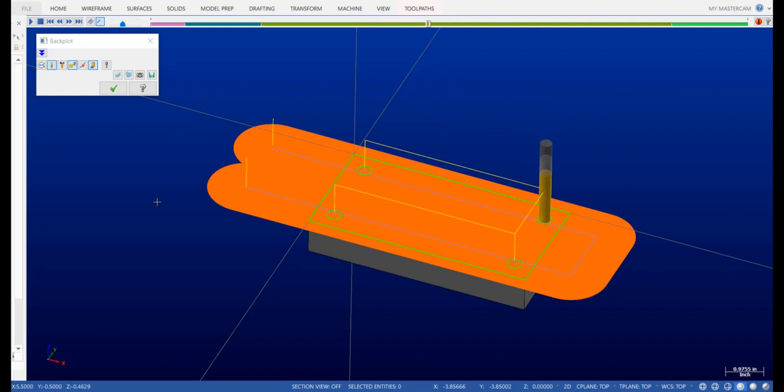And this is a good time for you to write an M97 subroutine or create an M98 subprogram that uses the same code but machines at a different work offset, so a different location on the table. So this is what the single part process would look like.